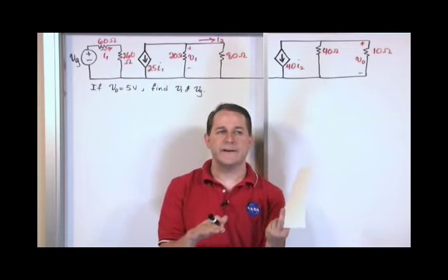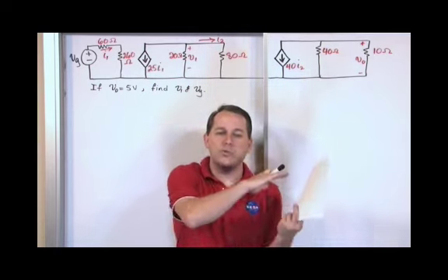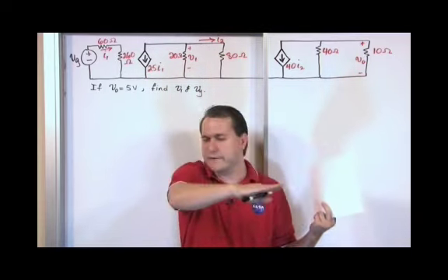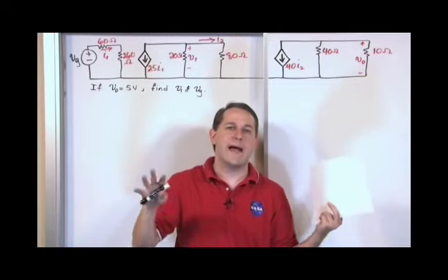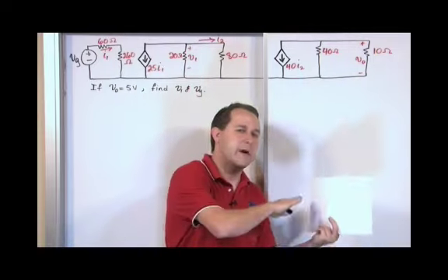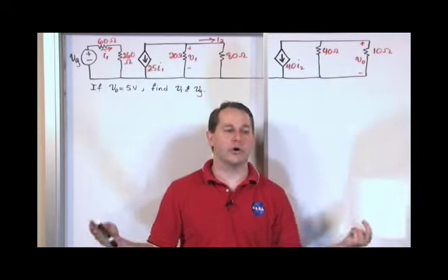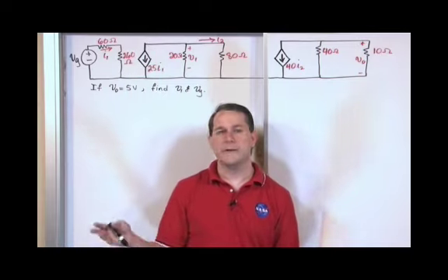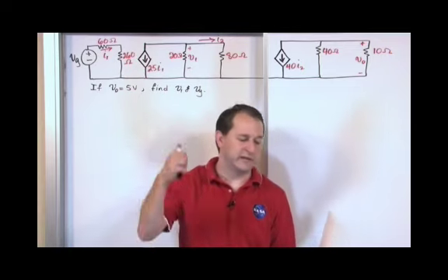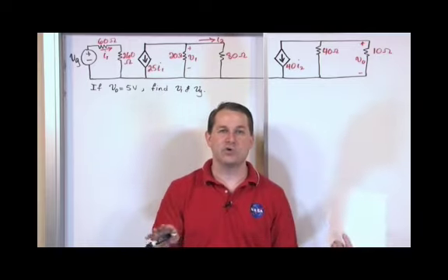In other words, since voltage is a change in potential, then you want all of those circuits to have as their base voltage, the bottom of their mountain, so to speak, at 0 volts, let's say. And then that way you don't have any discontinuities in the voltage from circuit to circuit to circuit. You want them all to be on that same level playing field. So this is very common in a car, for instance. The electronics in a car, they're all grounded to a common point. In your home, all the wall outlets, they're all grounded to a common point, which is usually outside your house. It's literally nailed into the ground. So the voltage reference of your entire house, 0 volts, is a known quantity for everything.